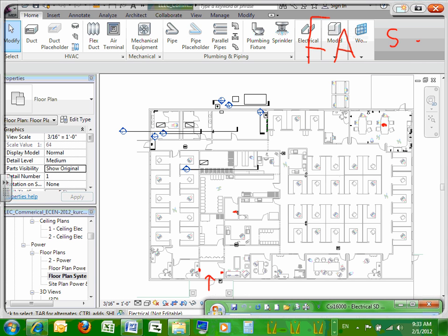I don't know, but it's going to tell the fire department exactly where to go, so they know they don't need to start searching over here. It's a 10,000 square foot building. It's not that huge. It makes tons of sense in a huge building, and it still makes a little bit of sense in a smaller building like this. But they know exactly where to go. This annunciator panel is telling them where the fire originated from, and especially if it hasn't spread, they can get there right now and put it out. So that's the purpose of having the annunciator panel. It's for the fire department.